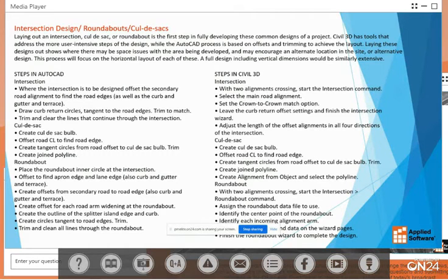to using AutoCAD. With Civil 3D, we need two alignments crossing. From that alignment, we can create an intersection. From Autodesk Vehicle Tracking, which is a part of Civil 3D, you have a roundabout tool. All that's required is one step in reference to what alignment, or one path, or an intersection. And if you had multiple roads coming in terms of the arms for your roundabout, Civil 3D addresses that in seconds.